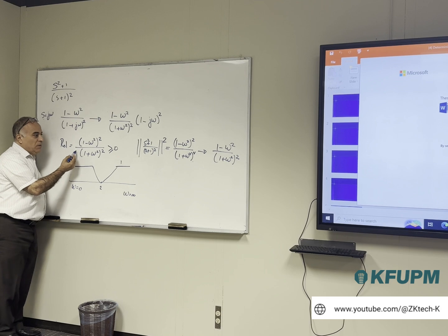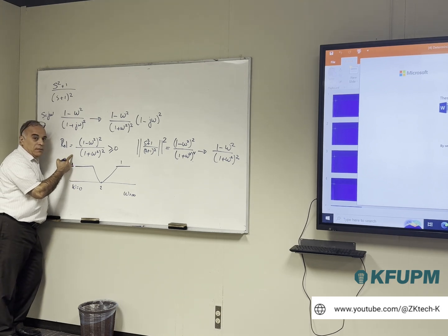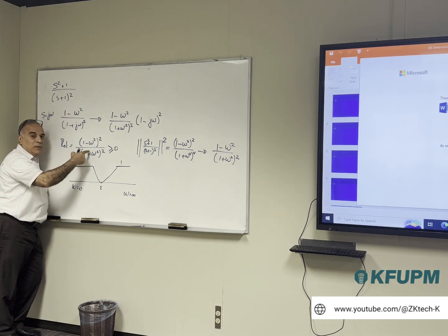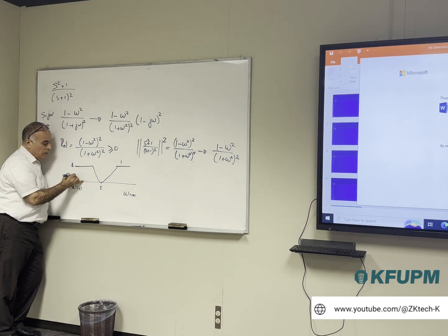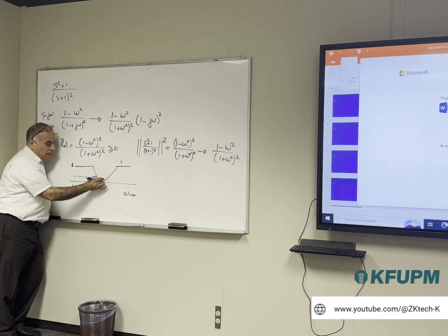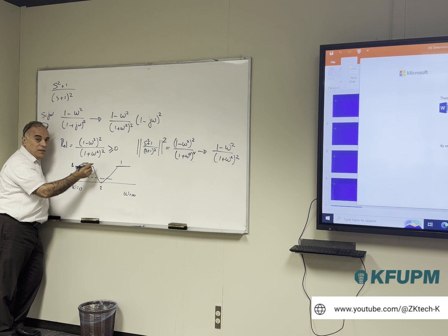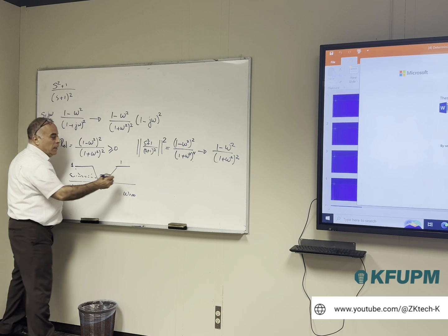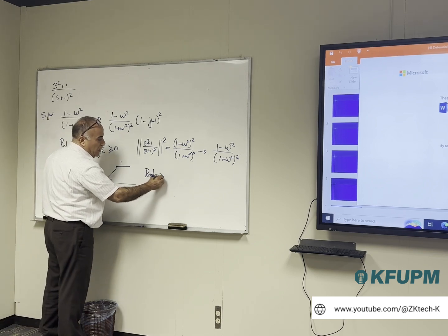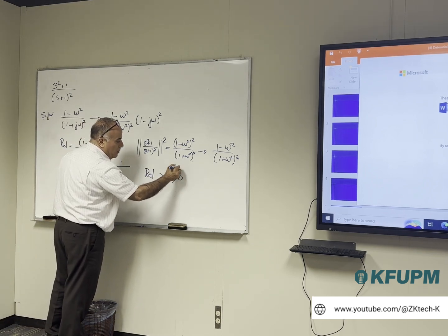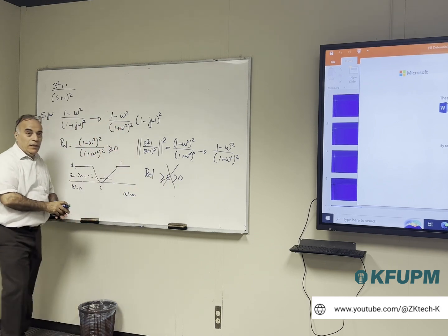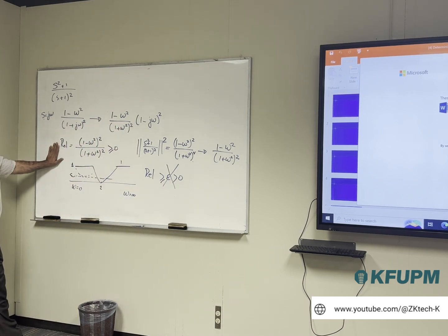So we are not able to find epsilon such that this real part will be bigger than epsilon. Everybody's okay with this? So there is no threshold here, and they say there is an epsilon. The real part is above this epsilon and above 0. There's none. So I cannot write real part bigger or equal to epsilon strictly positive. I can write this. So I know that the system is passive, but it's not strictly passive.